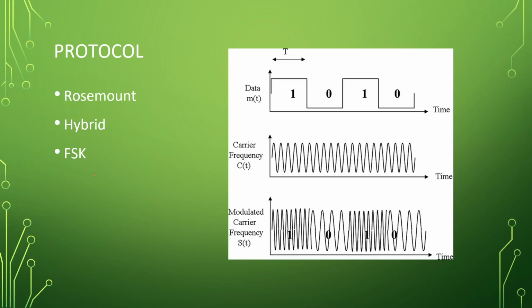This is why I have Rosemount here. That's who originally developed it. It is overall considered an open standard, as we talked about. The video talked about it at the very end. So anybody can use this. They say, here's the basis. You have to do these minimal things. You have to be able to tell us the 4 to 20 signal. You have to tell us this, blah blah blah. But if you want to tweak it slightly, you can do that. And I talked about that little file at the end that you had to have to actually decode all the information. So in that aspect it is good.